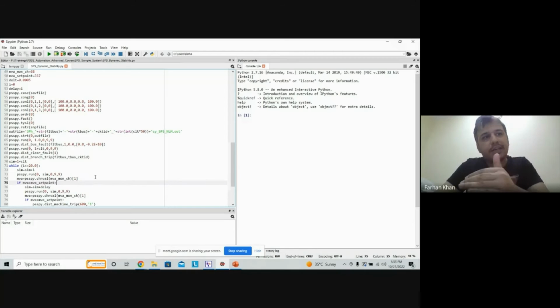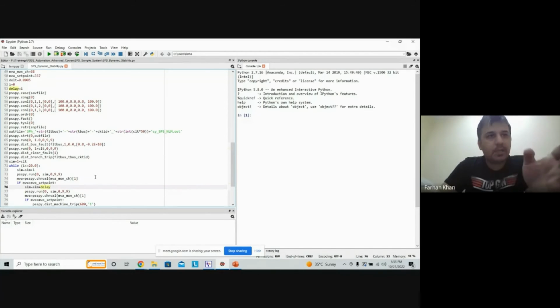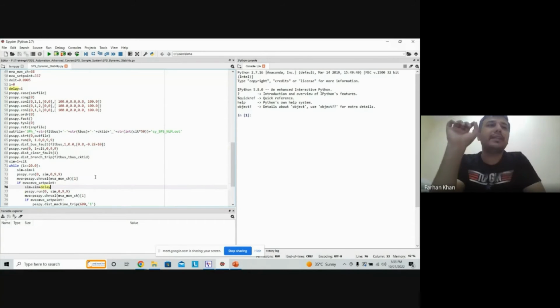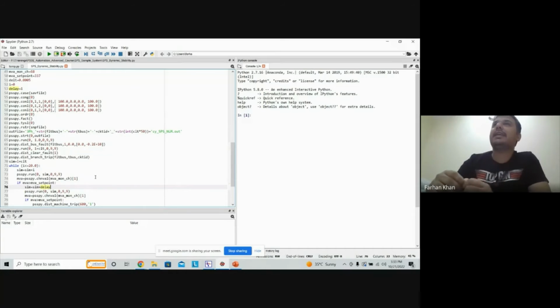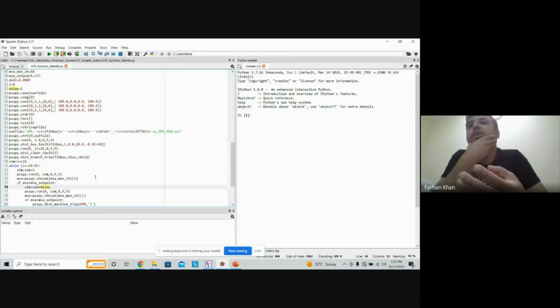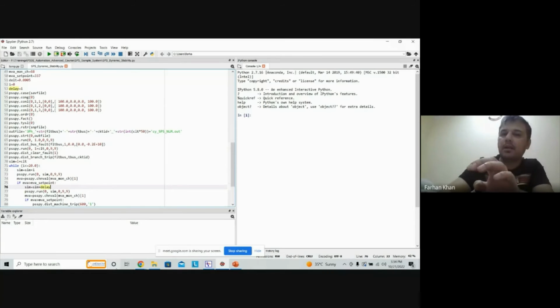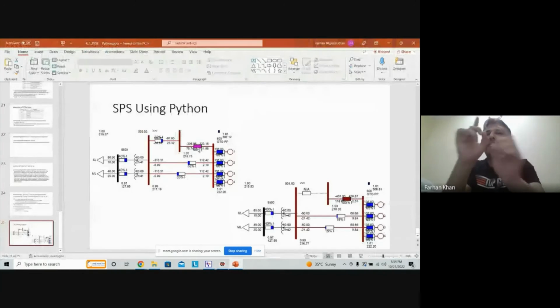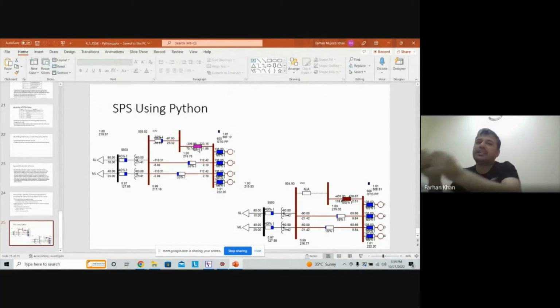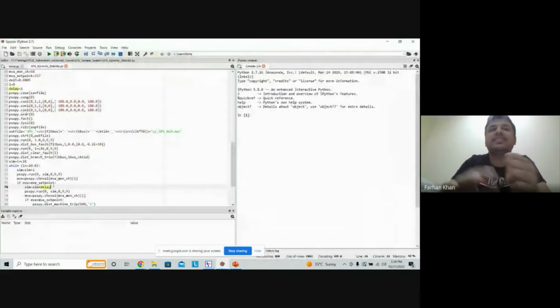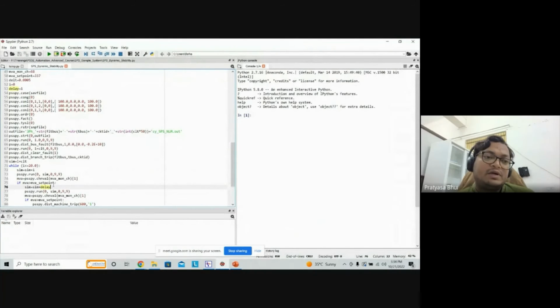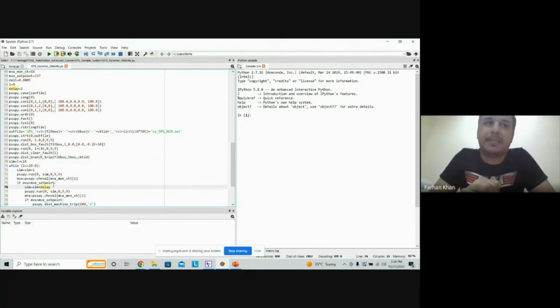then what I want you to do is, number one, sim is equal to sim plus delay. So what basically is this delay? This delay is like an inherent delay which we create during a time step. It is not necessary. For instance, if you want to type something instantaneously, you can do it at this particular time. What I am doing is, once you see that this particular transmission line is overloaded, wait for 1 second and then trip the generator. That is why I am giving this delay of 1 second, taking care of all those relays, breakers, and any other delay.